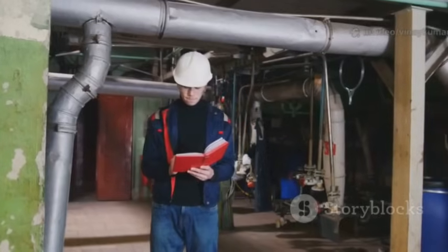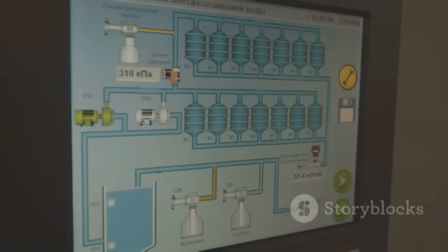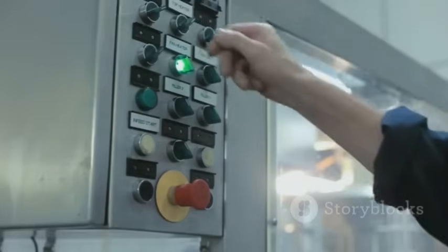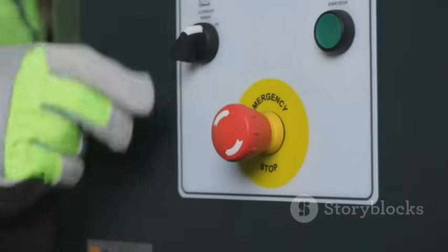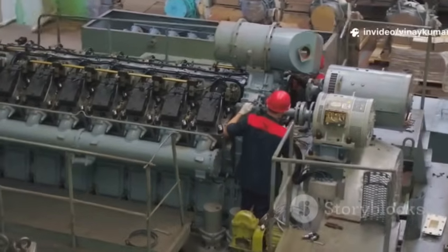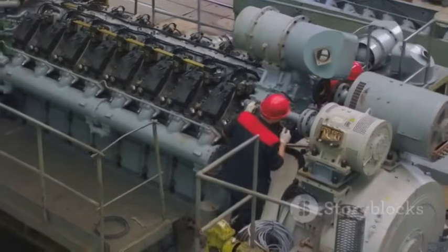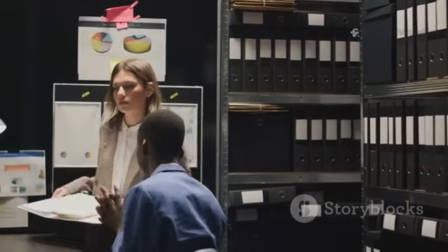They can't be locked away in a manager's office. They need to cover every phase of operation, not just the normal day-to-day stuff. This includes initial startup, normal operations, temporary operations, and emergency shutdown, including the conditions under which an emergency shutdown is required, and the assignment of shutdown responsibilities to qualified operators. They also need to cover normal shutdown and what to do when starting up the process after a major shutdown or turnaround. Every conceivable state of the process must have a corresponding, well-documented procedure.